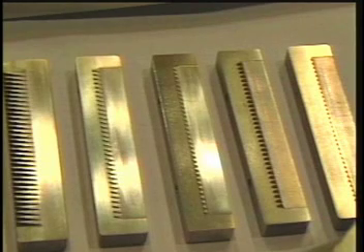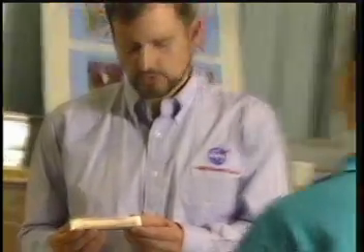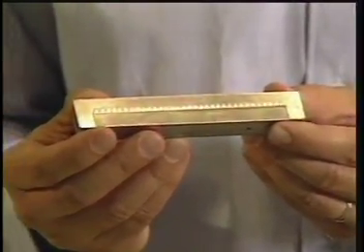Using the wind tunnel, we tested several trips with different shapes or geometries to see which one worked best to change the airflow from laminar to turbulent. Our wind tunnel test determined that this triangular-shaped trip was the best design for creating turbulent flow for the scramjet engine on this vehicle. How do you test the scramjet engine?